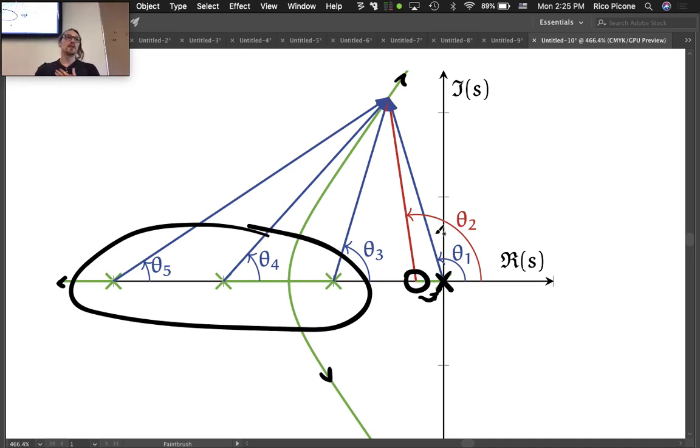But that's the general method. It's actually pretty straightforward. The idea is to put in an integrator because you want that steady state error to be good, right? So you put that in, and then you put in a nearby 0 to counteract its effects on the root locus, and you have to play with that 0 location in terms of how close it really should be to that pole and what kind of performance you get out of that. A lot of times you have to do simulation to really get a feel for where that 0 should really be. So we'll go through an example of that.